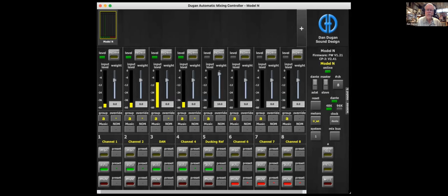Now, we're going to go from the levels of the microphones, that's the outputs, and we're going to go to the gains. This is what the automatic mixer is doing. So think of these green bar graphs as faders. The faders are all the way up at unity gain when I'm talking, and the other channels are being suppressed. And when I don't talk, all the gains come up to medium gains that sum to the gain of one open microphone.